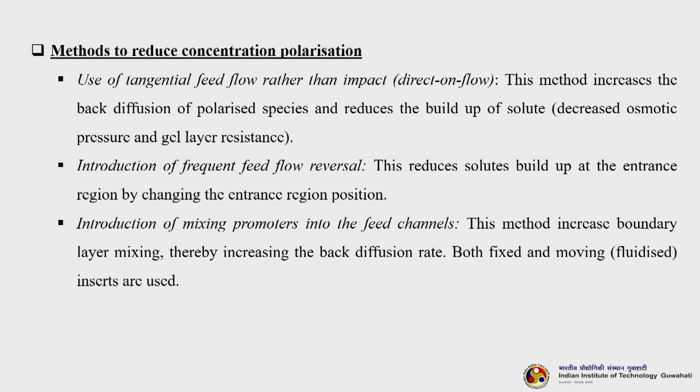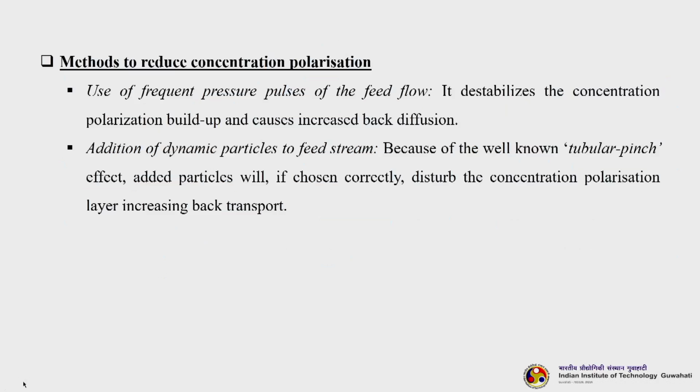Then the next one is introduction of mixing promoters into the feed channels. Now, this method increases boundary layer mixing, thereby increasing the back diffusion rate, right. Both fixed and moving inserts are used. Then use of frequent pressure pulses of the feed flow. This destabilizes the concentration polarization buildup and causes increased back diffusion. So, you are doing the pressure pulsing.